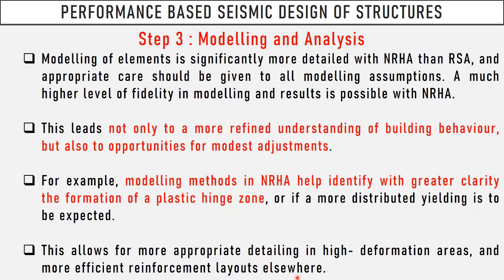If you go more complex, if you want to model everything in your structure, you put more complexity in your model, and the results may be problematic after all. Keep it as simple as possible, because it doesn't mean that you have more reliable results if you have every member in your mathematical model.